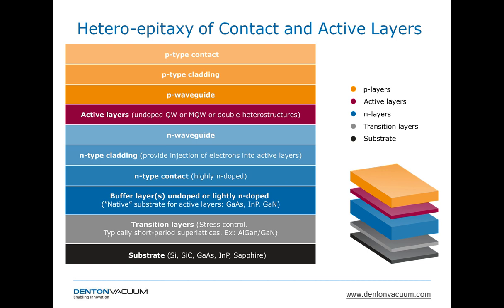Although it's true that some deposition technologies, like IBS, result in higher stress films. There are ways of reducing stress. We have known that ion assist can, in some cases, reduce stress in the films, but the primary driver is the overall stack design.